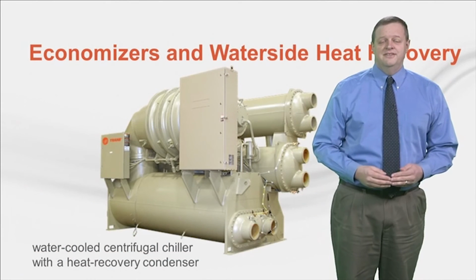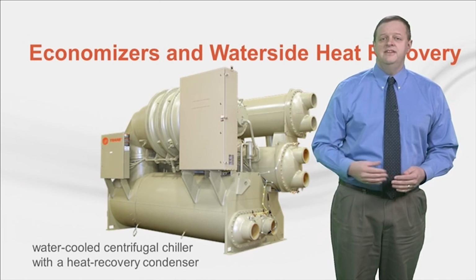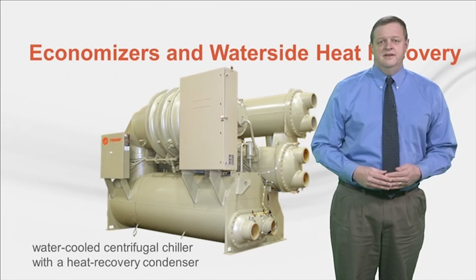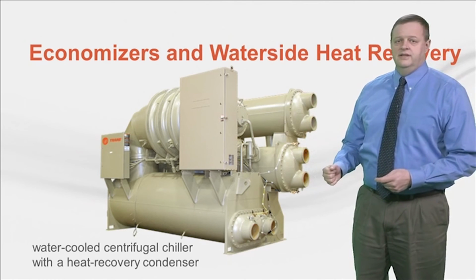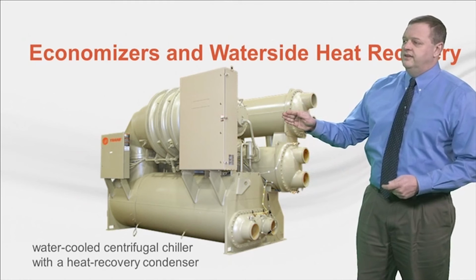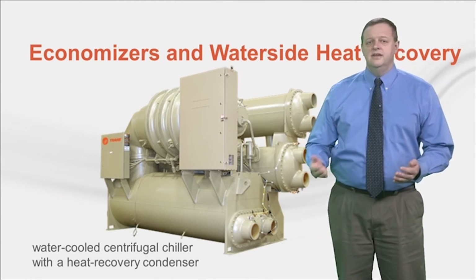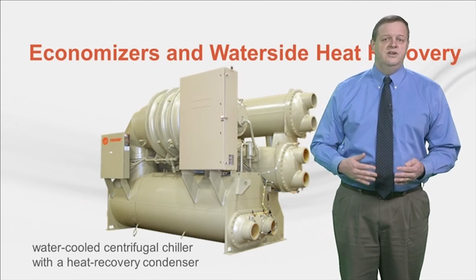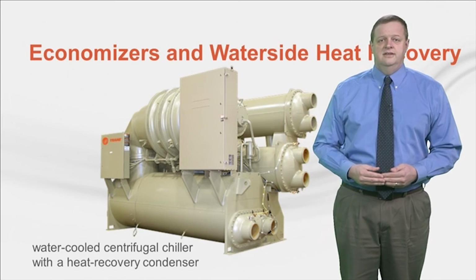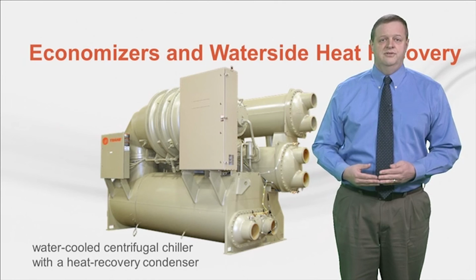While an Airside Economizer reduces energy use in most cases, there are some applications where the cooling energy saving benefit of the economizer competes with other components of the system. The first example is heat recovery. When a water chiller is used to provide cooling, the heat rejected by its condenser can be recovered to serve a useful purpose in the building. In some cases, this heat is used for preheating service water for restrooms, laundry, showers, or other processes. In other cases, it's used as reheat for humidity control or zone temperature control.